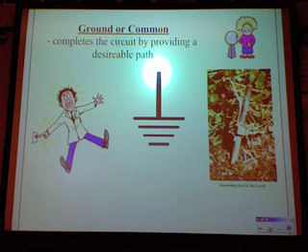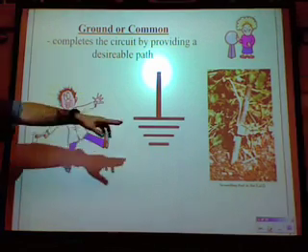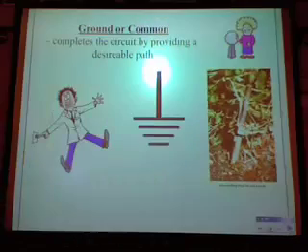That's why these wall plates are grounded, because there's electricity right there. If wires were to come loose and touch that, and then I touch the plate, I get shocked. And I don't mean just, ooh, it hurts shock. I mean, ooh, I'm dead shock. So by taking that wire and connecting it into the earth, we have a ground connection.